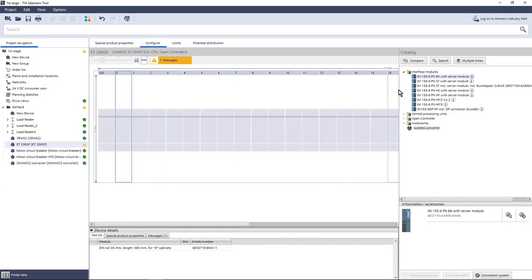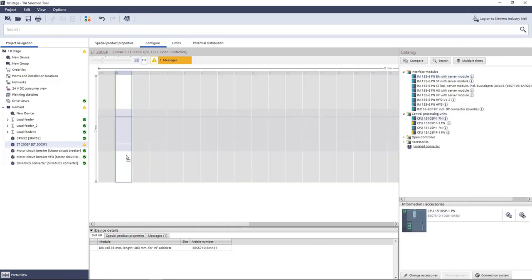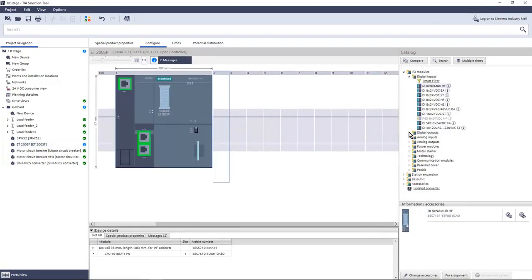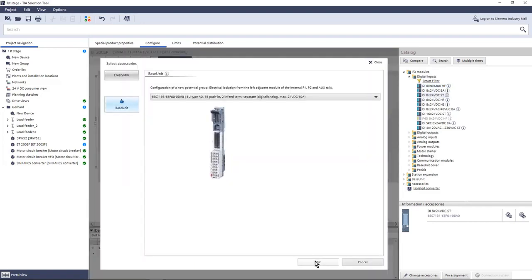Okay. Now, if it's okay with you, I would like to go into another device. So I click here and now let's go with the ET200 SP. Basically we go into IO systems, and here we will go with the ET200 SP as IO, with the CPU and controllers that we will use, and we go directly to configure up here. Now you will have a really nice rack view when everything is mounted.